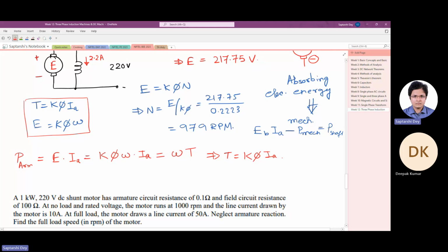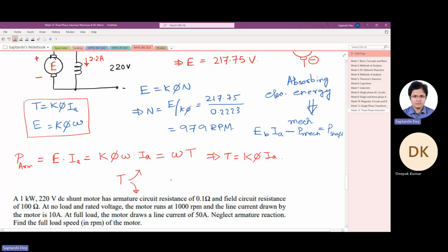So why I'm saying torque developed is that the torque is developed by the motor, and there is some loss, mechanical loss, and core loss is considered here. Core loss is also reflected as a mechanical loss because it's nothing but eddy current braking and all. Now, the developed torque has to supply those two losses, and what is left goes to the shaft.